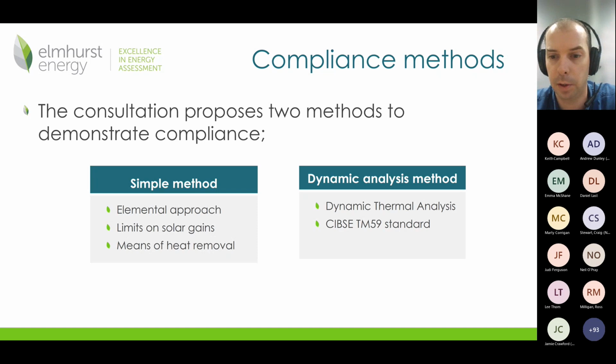And there's different standards depending on whether you can or can't. That is not done in SAP anymore; that's a separate procedure completely. The dynamic analysis method is using dynamic thermal analysis, or DSM, sometimes it's known as, against an existing standard known as CIBSE TM59. That's basically 3D modeling, much more in depth, and gives much more design flexibility than the simple method for buildings that struggle. Either method is acceptable, but the simple method is very prescriptive.